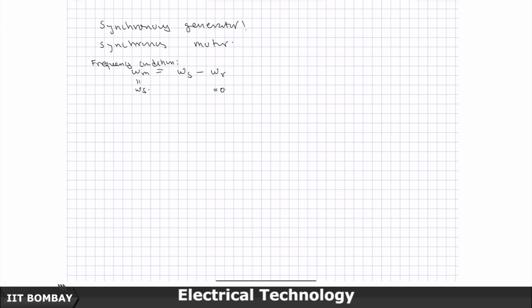So when the magnet is rotating and the winding sees rate of change of flux, induced EMF is generated. If there is nothing connected, open circuited, then the mechanical power required for steady state rotation is 0, because speed is constant. I have neglected friction, windage losses, and all other parasitic losses in the machine. There is no electric output, so there is no mechanical input also required, and once you set up the speed, it is like a perpetual machine which will keep on running under ideal conditions.